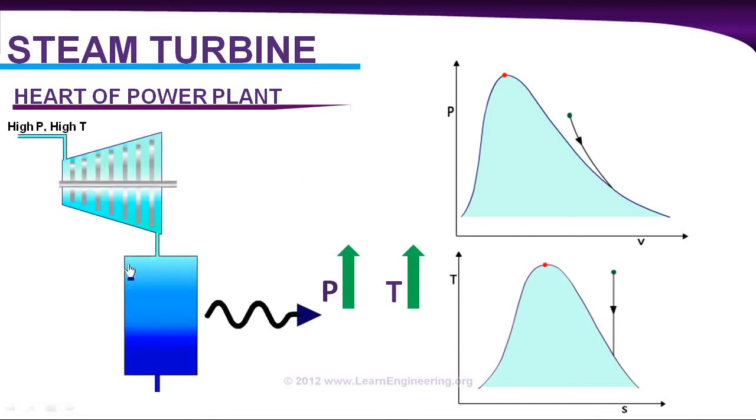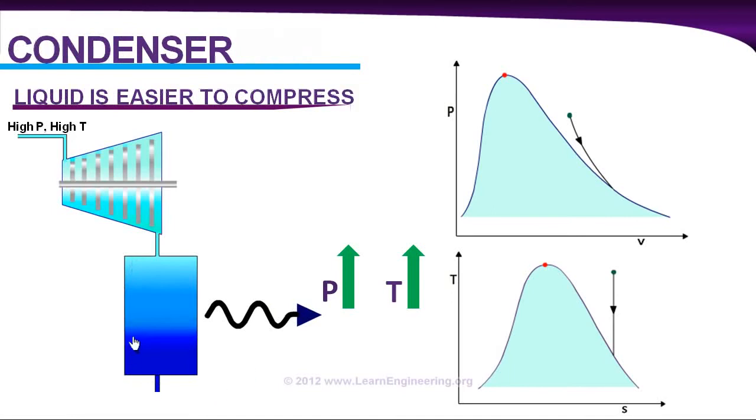Like this. You put a condenser over here that can reject heat to the surroundings. So vapor will get transferred into liquid state. Now this process can be drawn in PV and TS diagram like this. And during heat rejection there is no pressure change because fluid is free to expand. And obviously this is a phase change, so temperature cannot change. So this is in TS diagram.